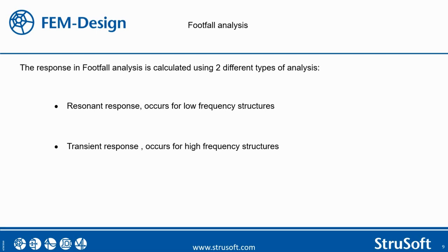Transient response occurs generally for high frequency structures. So if the structure is relatively stiff, then the transient response will be more significant than the steady state. It is also assumed that the resonant response can be induced up to the fourth multiple of the walking frequency. So for example, when the maximum walking frequency is about 2.5 Hz, the limit for resonance possibility is about 10 Hz of the basic natural frequency.